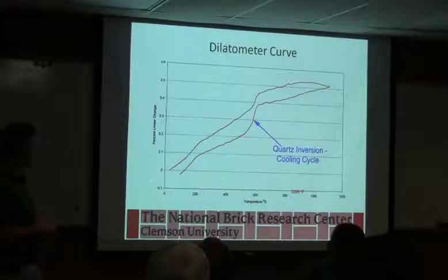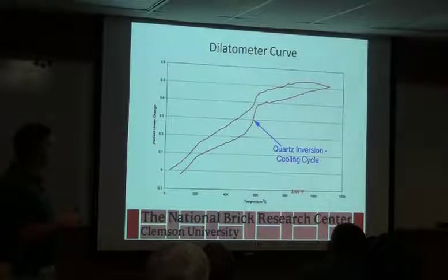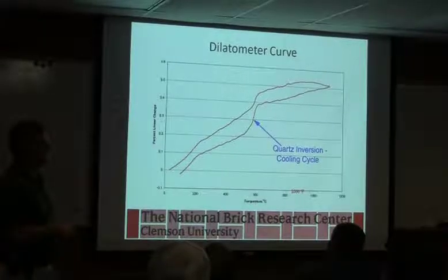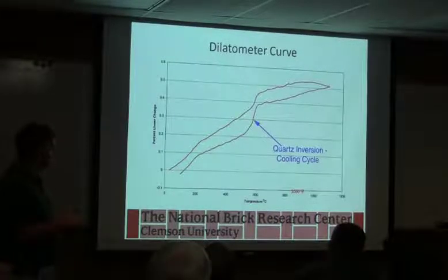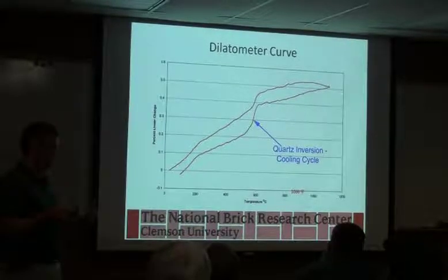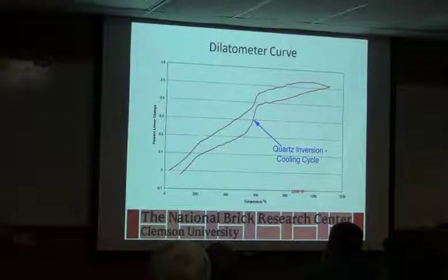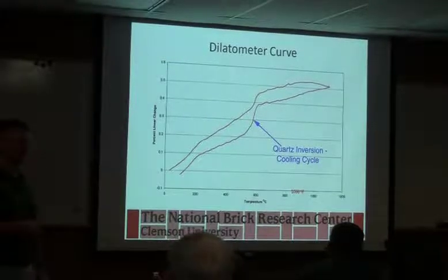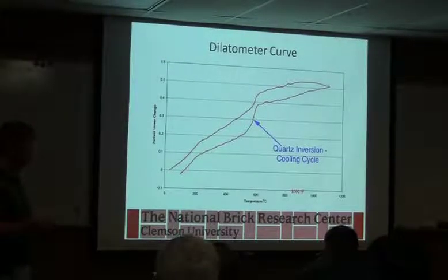This is showing you that as you're heating it up, look at that, 573C is the equivalent on quartz as well. Going up in temperature, it did its expansion, and going down in temperature, it did its reduction. All of that, again, leads to stress in the product, and whether that stress is beyond what your product can absorb will dictate whether you get a crack or not.